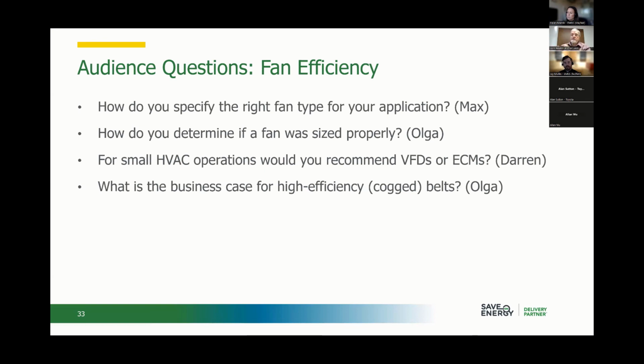Doing a field test, here's a pitot tube, pretty inexpensive. Here's a manometer, a pressure gauge that is suitable for use between the pitot tube and this. You can soon start measuring flow. And if you need help on that, give me a shout, okay?